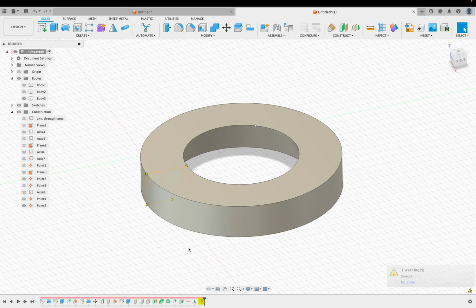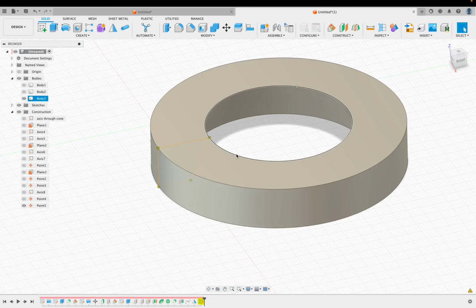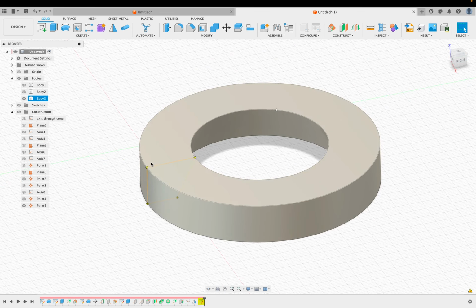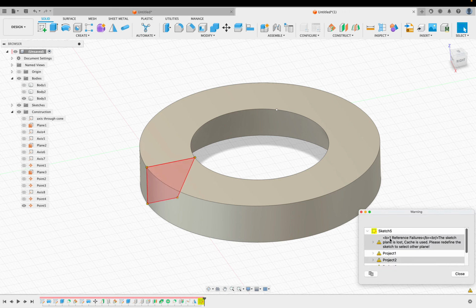and this is the first time you guys are seeing it, which is completely fine. You will see this in Fusion a lot. It's giving me these yellow-orange lines, okay? And the history is marked with this. Now, this is telling you that you're losing a reference. This is important because once you lose your reference and if you start making changes, your model will not adapt to those changes. So let's see what's going on. We can click this exclamation mark on the right hand side.